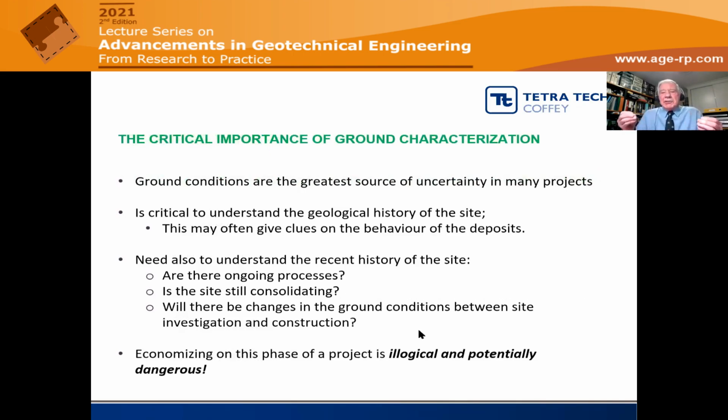Now, it is critical, as I mentioned before, because ground conditions tend to be the greatest source of uncertainty in many projects. And so we need to understand the history of the site, because that may give us clues on the behavior of the deposits. And we also need to understand the recent history of the site, because just because we've come onto the site for our project does not mean that time zero starts from when we walk onto the site.